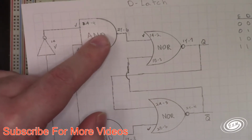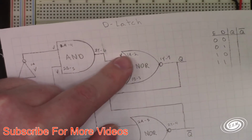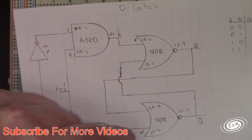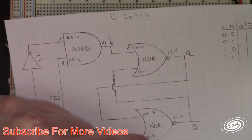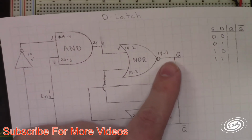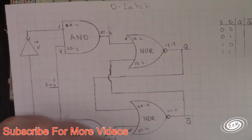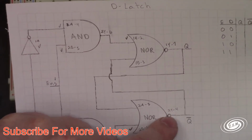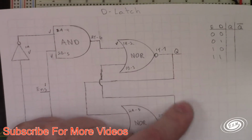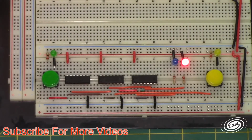And from the AND gate here, which is the output pin 6, I went to pin 2 of NOR gate 1, and then this AND gate was pin 3, and I went to NOR gate pin 6. And then I connected the output of NOR gate 1, which was 7, into pin 5 of this NOR gate, and pin 4 of this NOR gate, which is the output, to the input pin 3 of this NOR gate. And I hooked some LEDs up to Q and Q not. So that is how I did that.